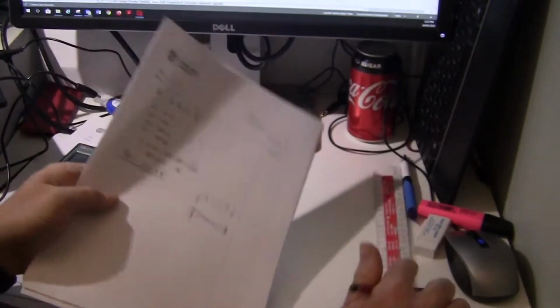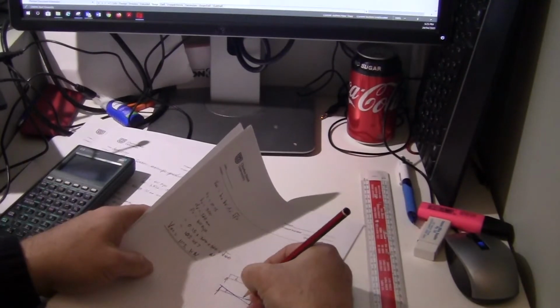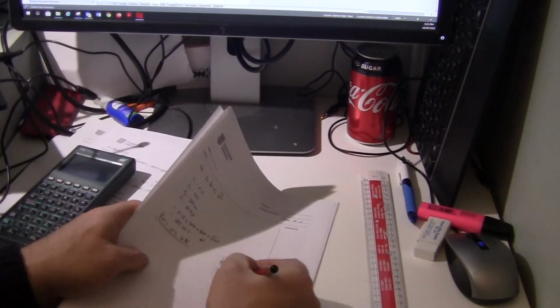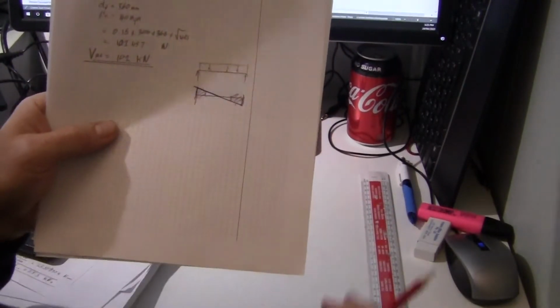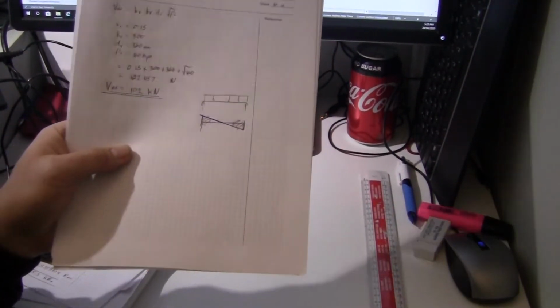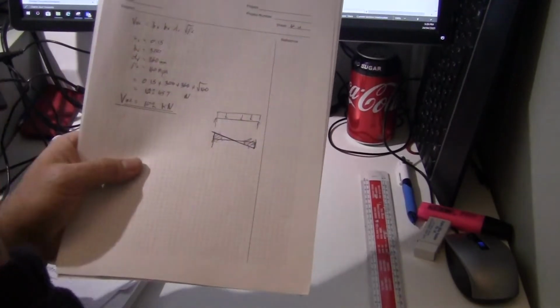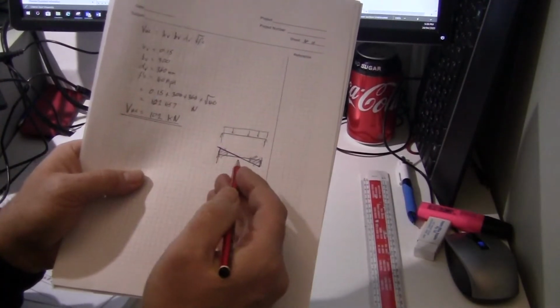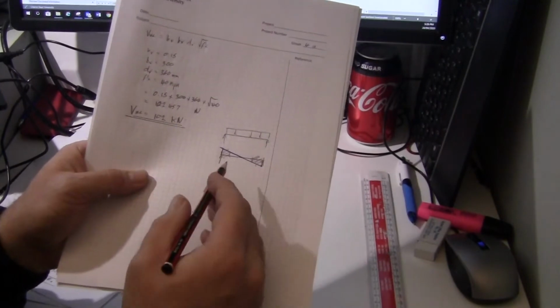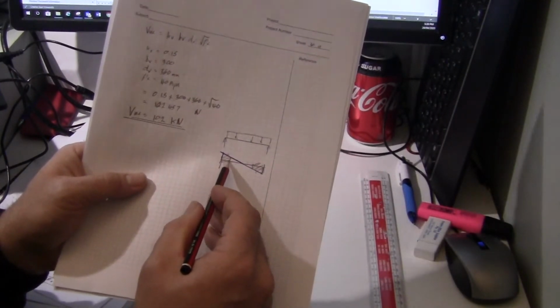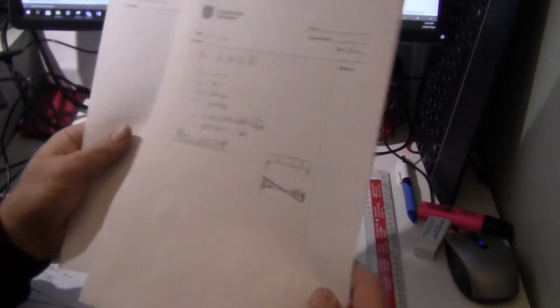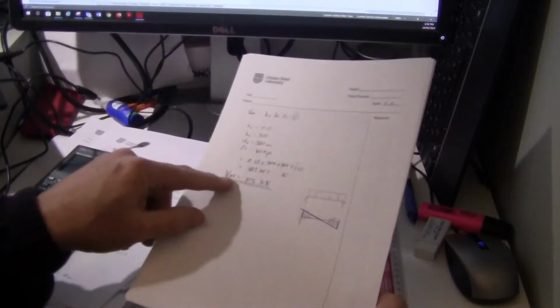And so what you might find is when you do a shear check, you might only need shear steel in the ends of the beam, and in the middle of the beam you can get away without it at all. So there are often areas in the beam where you don't need shear steel, and where you do. And when you come to situations like this, there are rules about how far beyond that point you have to carry the rings, and that's in the details about detailing reinforcement. But let's get back to our point.